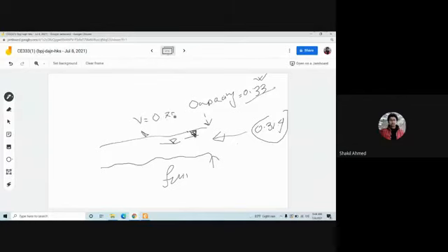0.78. Clear? Yes, sir. When it is a full flow, that means equal to the capacity, then this is the 0.78. But since your flow is less than the capacity, which is 0.314, that will be partial flow velocity Vp. This is V full. Are you following me? Yes, sir.